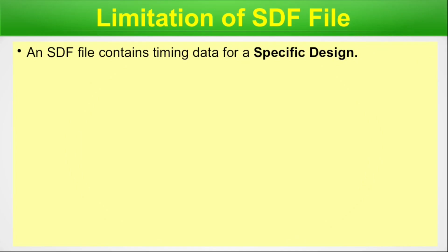This is very important because SDF is not for the entire standard cell library. It is not for any other designs, and to be very precise to the point, an SDF is specific to the design on which you are working. If you go to another design, the SDF file will be completely different. For one particular design, one SDF will be there.